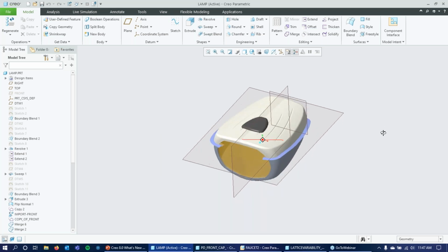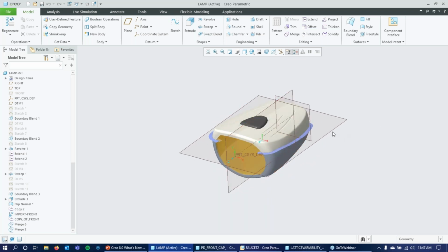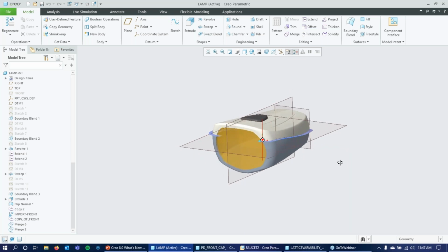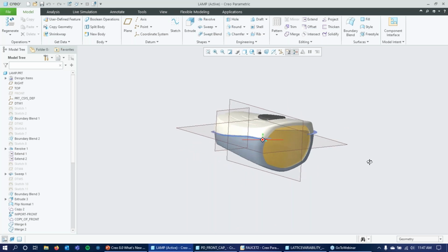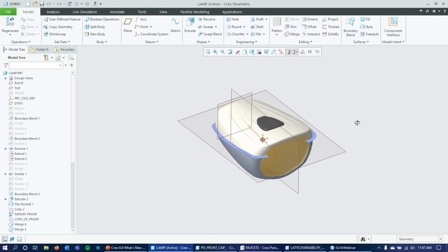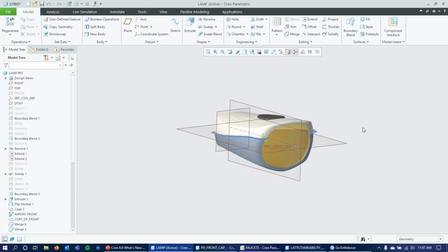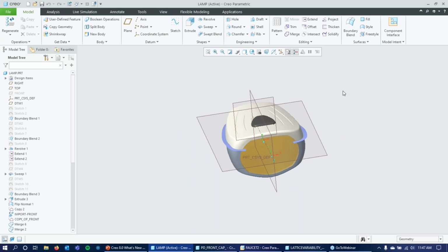This is a good example because the top plane is a bit extended since we're kind of working on this top plane, and we can see how this datum fill display makes viewing things in 3D just look a little bit better and a little bit more realistic. We can disable the plane fill display if we'd like, and this can be done through the InGraphics toolbar up here. So where we would usually choose to hide or display various datum features, we now have an option for plane fill display, which we can easily enable or disable whenever we would like.